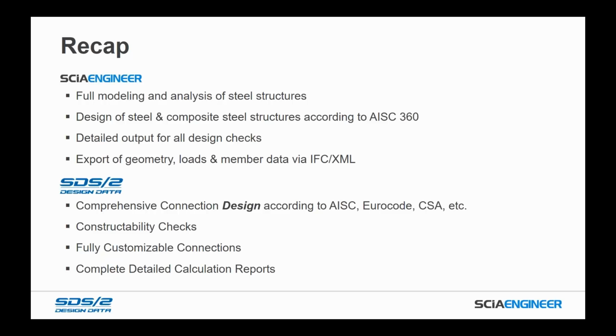For SDS2, Steve really went through that comprehensive connection design, not verification, of those connections according to the AISC codes, but also Euro codes, Canadian codes, Australian codes. There's other standards that exist in SDS2. Those are really nice constructability checks, not just, hey, does my connection work, but hey, does it actually fit? Can it actually be built the way that I'm saying it can, so you don't run into any of those issues later on down the road in CA phase.